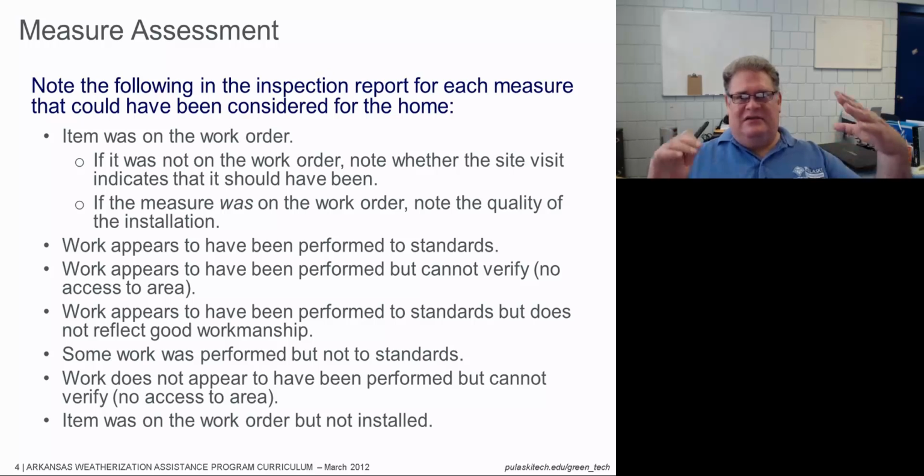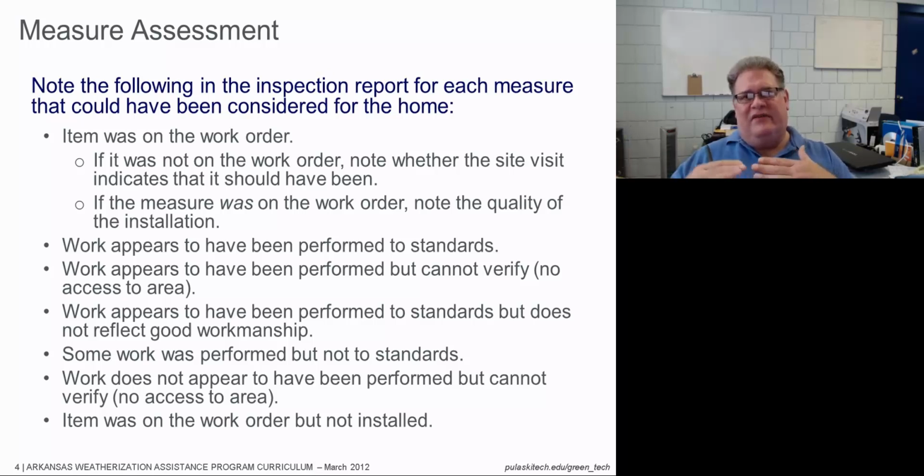So contrast that to the work does appear to have been performed. In other words, they've got empty insulation bags, they have empty tubes of caulk, they have screws and pieces of cut-off material, paint brushes with primer on them. So it does appear as though they did get into an attic, blow insulation. You can see some photographs of the insulation that they put in there, but they came back and put a repair in the air barrier, which is now wet, and you don't want to have them pull that off and cause a rework. But it appears as though they've done it, but there's no access there.